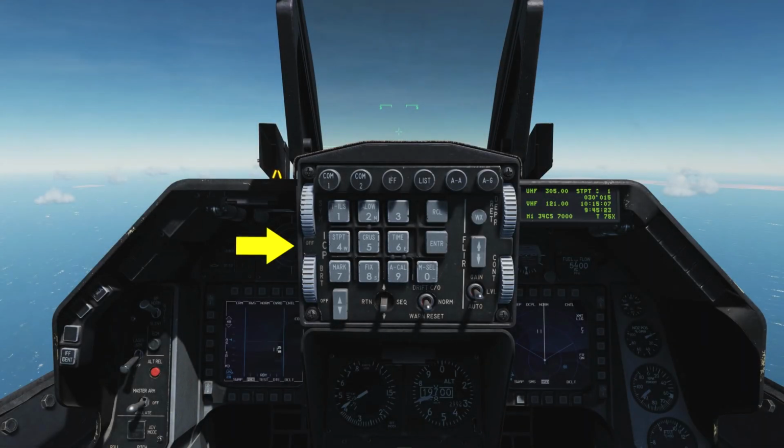The Integrated Control Panel, or ICP, fills the top portion of the center instrument panel and is one of the core systems of the Communications, Navigations, and IFF, or CNI, in the Viper. We'll talk about specific functions in later videos, but an overview of the functions includes the following: Radio 1 and 2 control buttons, the Identify Friend or Foe button, the list option that displays options on the Data Entry Display, or DED, select either air-to-air or air-to-ground master modes, wheels to control brightness, symbology brightness, reticle depression, and raster contrast. The raster selection is not applicable to this F-16 version.